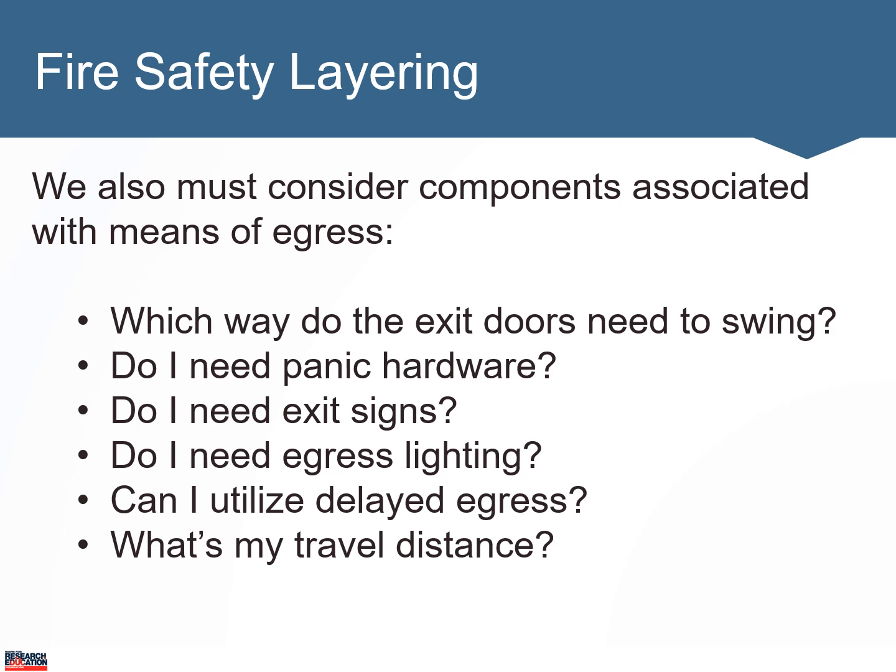Fire detection systems are going to detect a fire and provide for early warning along with the fire alarm system, which will provide the early warning, giving people more chance to safely egress the building. And with fire suppression, we're actually going to fight the fire automatically as people are exiting the building, providing protection to the occupants, providing a limitation on the size and spread of the fire with our suppression system.